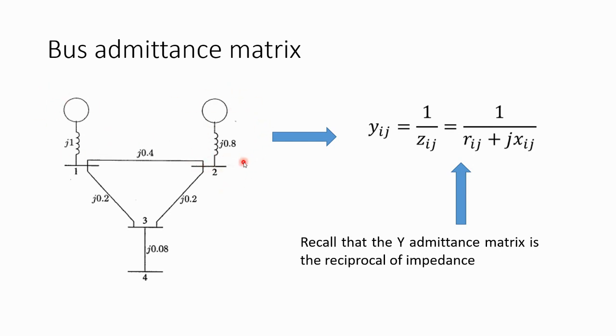Generators are understandably very efficient in injecting the power they generate into the network. In that case, we can conclude that the resistance in the generators is also very low, and we can ignore it in our analysis. That is the reason why the impedance given to you is only in imaginary form.